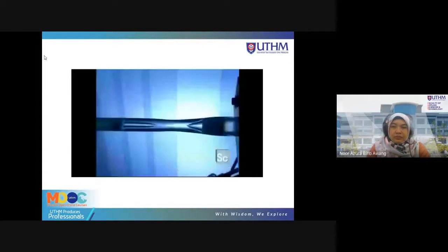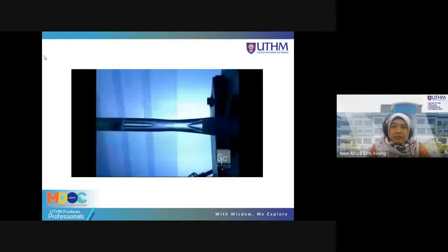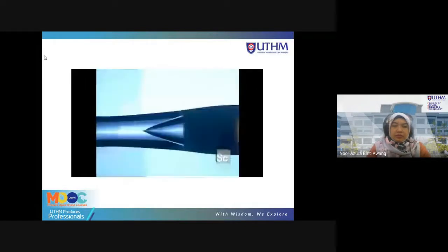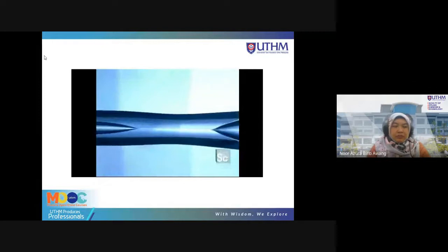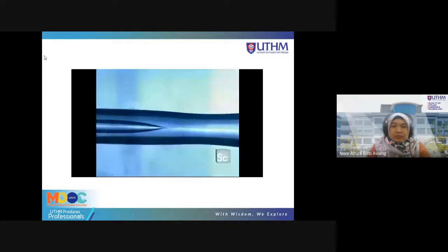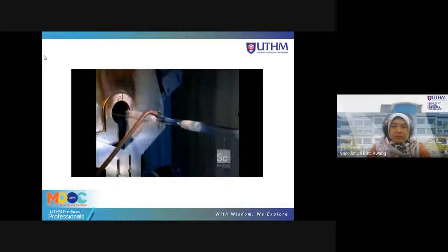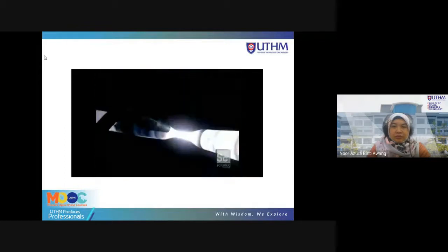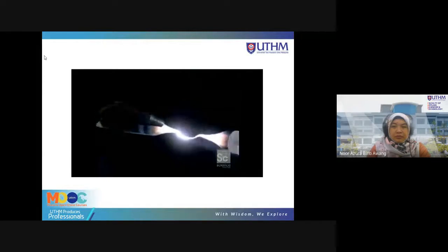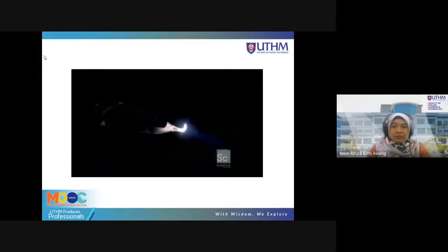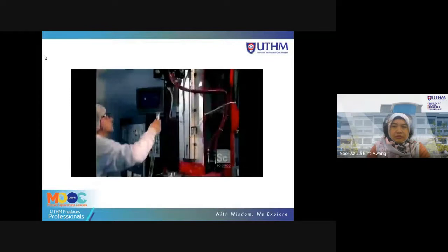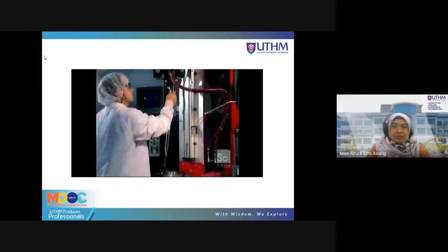The internal structure of the optical fiber has been achieved, but it's in the form of a big bulky rod called a preform. So the next step is to thin it out. First, they excise the preform from the uncollapsed section of the glass tube. Then they install it vertically into the drawing tower, which will draw out the final shape.